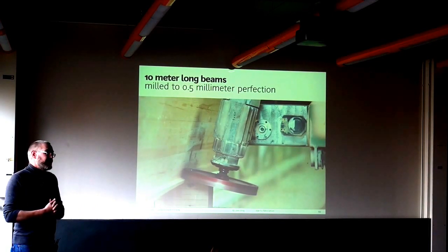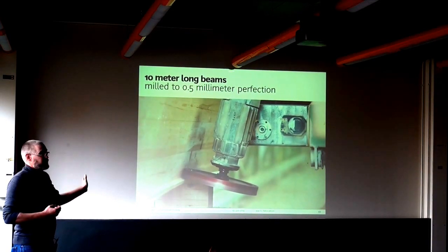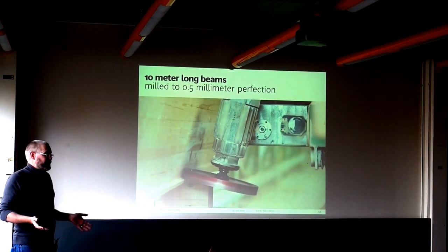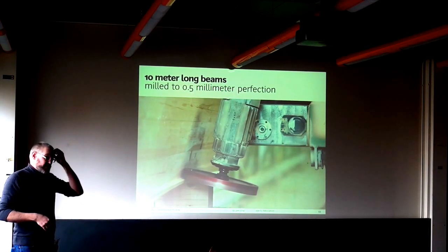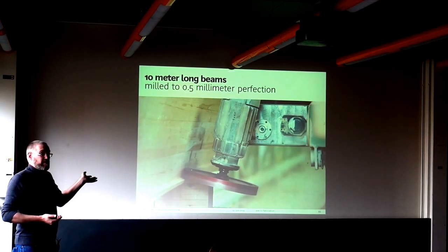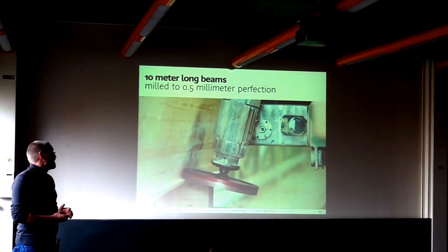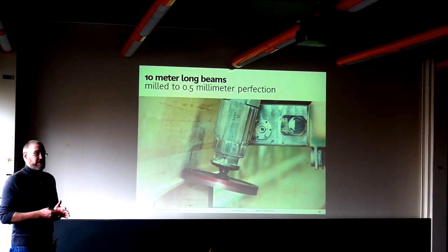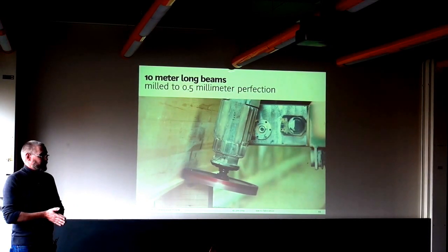So how do you control the climate, or do you maintain the piece with steel frames, for instance? No, the conditions in the fabrication are controlled in any timber fabrication where you go. We're usually working at a certain temperature range and a certain moisture range. The things are more or less shrink wrapped when they are sent to the construction site, and sometimes they even have to be controlled on the construction site, especially when you try to glue things on site. It has to be in a controlled environment.